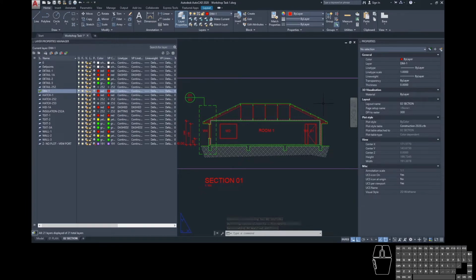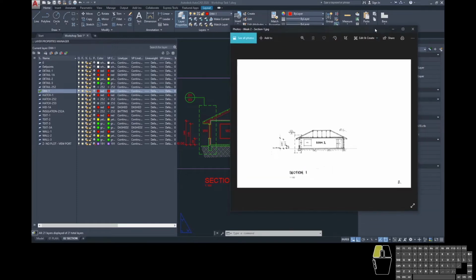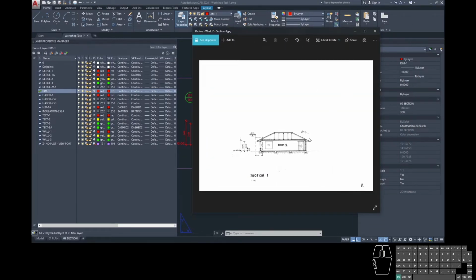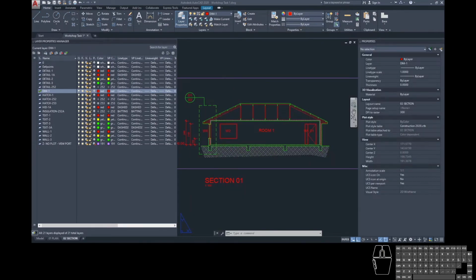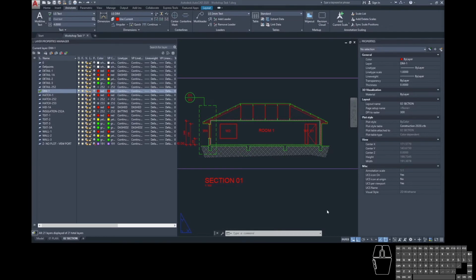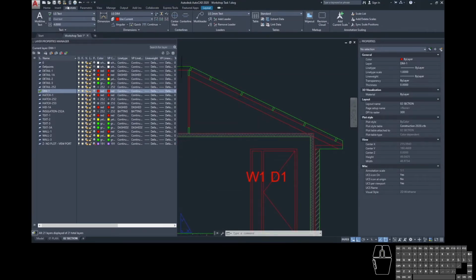The last thing that we're missing is that angle dimension up here. If we look at the original drawing on here, you can see we've got these two lines, we've got our angle dimension between them. When we come to do that on our screen here, we're going to be using the angular dimension, so under the Annotate tab. This usually says linear. If you use the drop down, you'll have the option for angular.